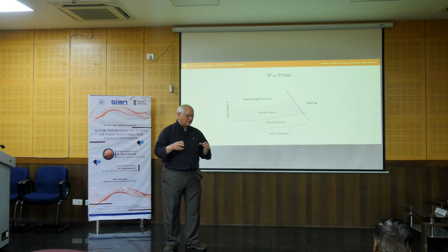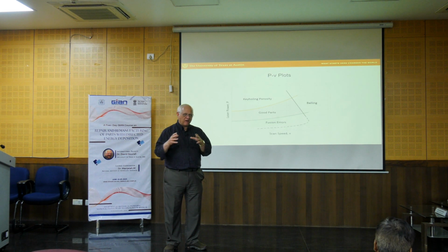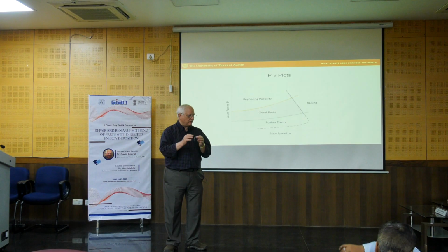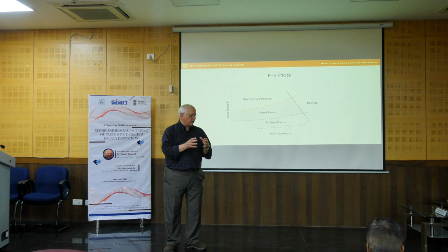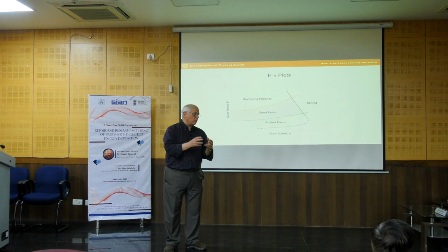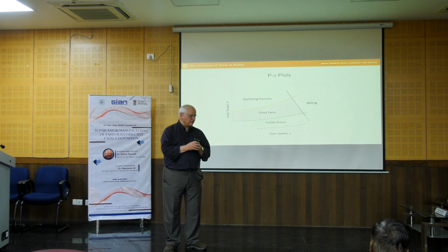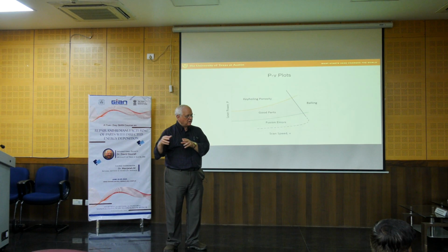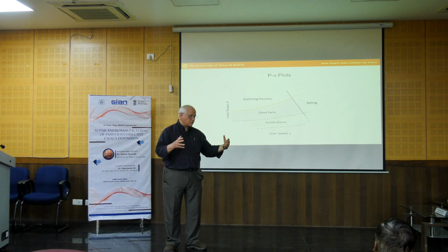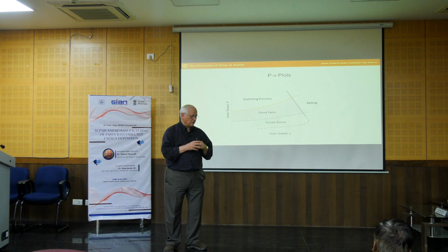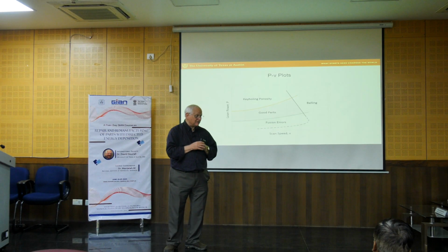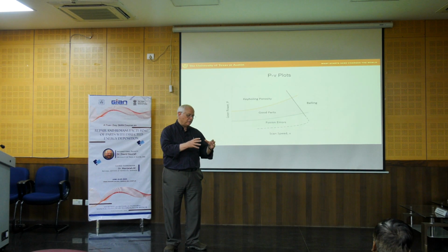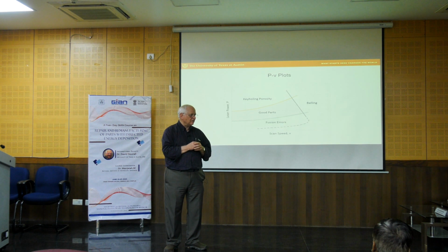But my experience is that powder bed fusion tends to find applications where the parts have fairly complicated geometry and we don't care that we're building at a low speed. So perhaps small parts with complicated geometries make us lean towards powder bed fusion. Whereas if I have a large part, or I'm not so concerned about the geometry, because you can produce very nice parts in DED in terms of quality, then I lean towards DED personally.